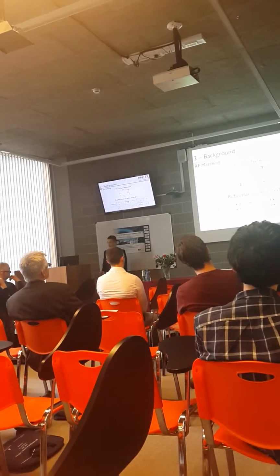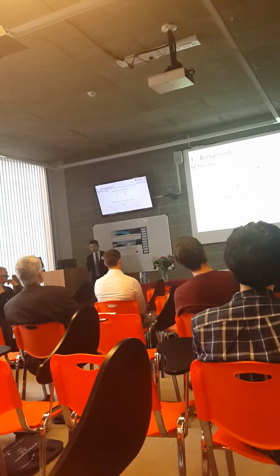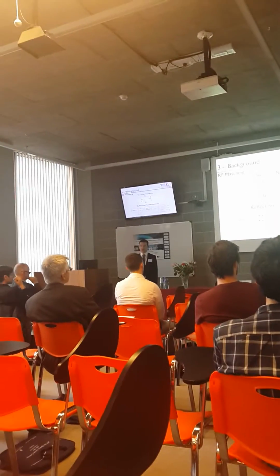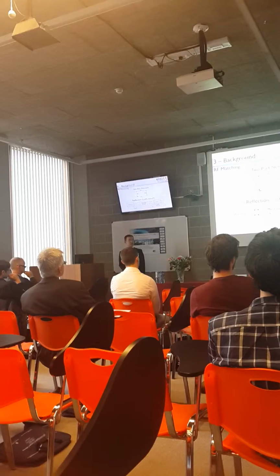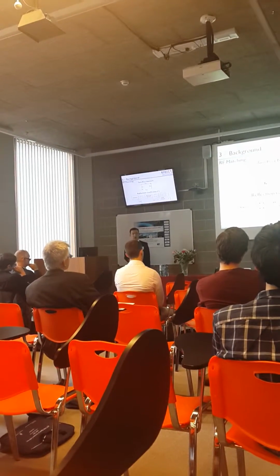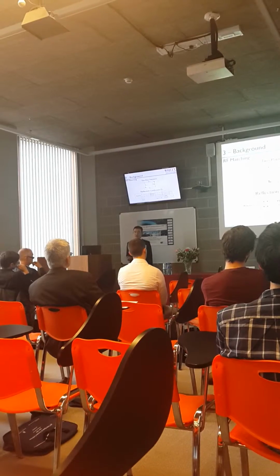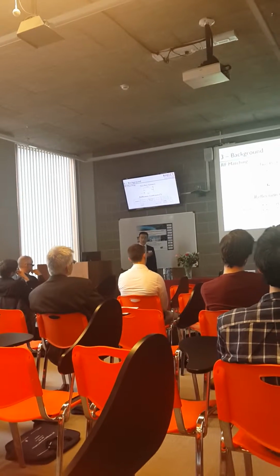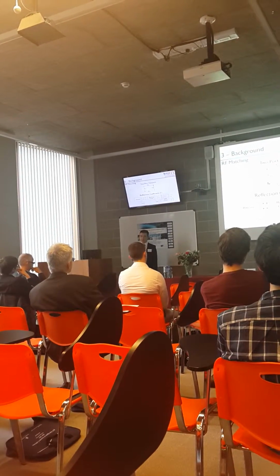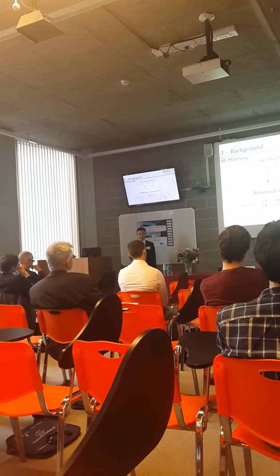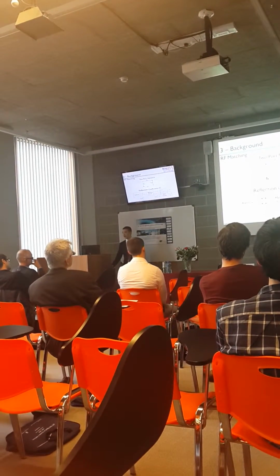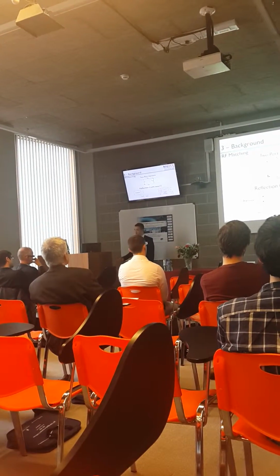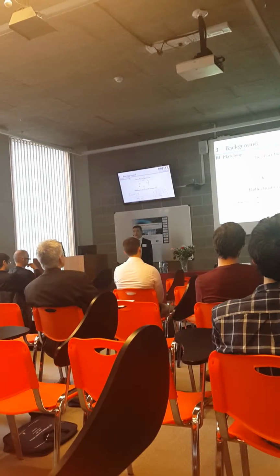The antenna, the matching circuit, and the low noise amplifier. Particularly for the low noise amplifier, it has the source reflection coefficient and the load reflection coefficient. Normally, the source reflection coefficient contributes to the noise figure, while the load reflection coefficient contributes to the gain. Therefore, there exists a gamma opt at the input side for the lowest noise figure for the low noise amplifier. And if we bypass the matching circuits, the gamma opt is designed to directly match the antenna. We could get rid of the input matching circuit.